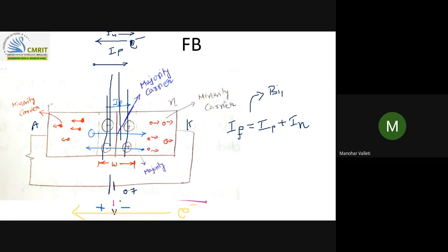And whether it is drift current or diffusion current, you try to understand. Electrons were more here, electrons are less here, and until that barrier is broken down, till then only this external supply is needed. Once the barrier is broken, later the movement is free flow from N to P and P to N. So the forward current is diffusion current.